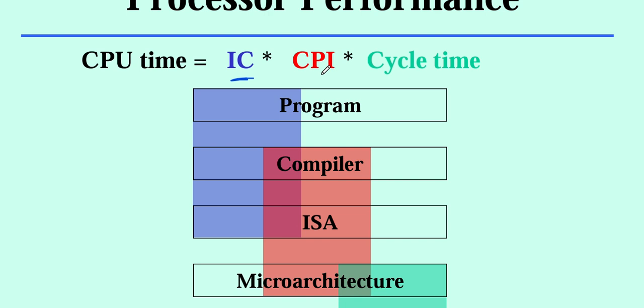You get it? Now, the two things which usually change are the CPI and the cycle time. CPI stands for clock cycles per instruction, right? Now, assume that this processor is so good because the CPI is one. Do you remember I said the CPI is one from the previous slide? Because you use only one cycle to execute everything, one big clock cycle. However, if your CPI is one, have you talked about your cycle time? So that's one thing we consider. So performance is three things: your CPI, your cycle time, and the instruction count.